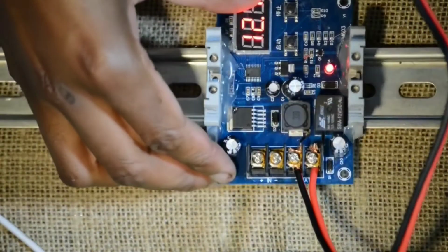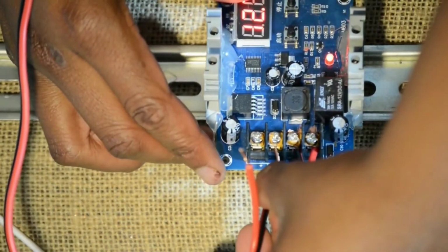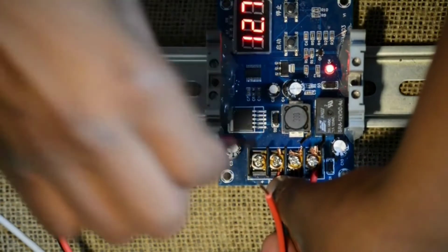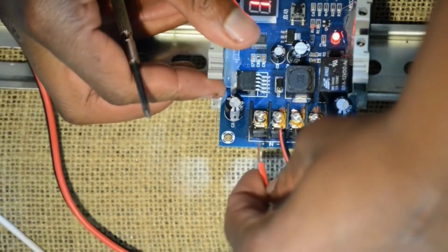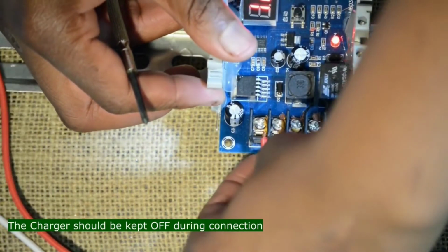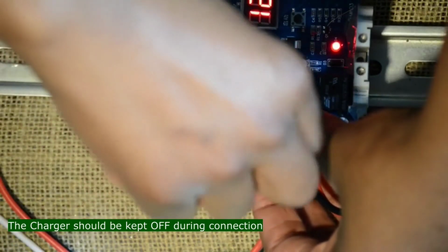And so now what's left to do is to connect the input, which is basically the output of the battery charger. Realize at this stage it's not yet on. I have not switched it on yet, and you should only switch it on once you've done the connections. And also be careful of the polarity, right? You have a positive and then you have a negative.